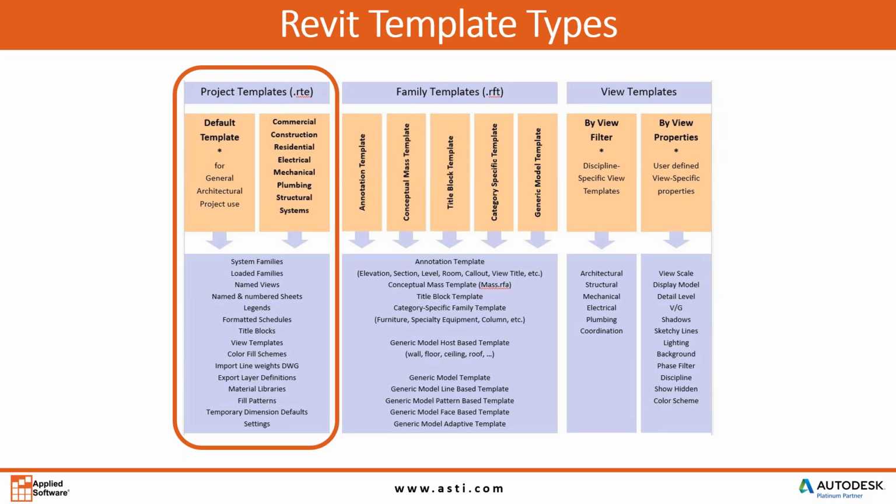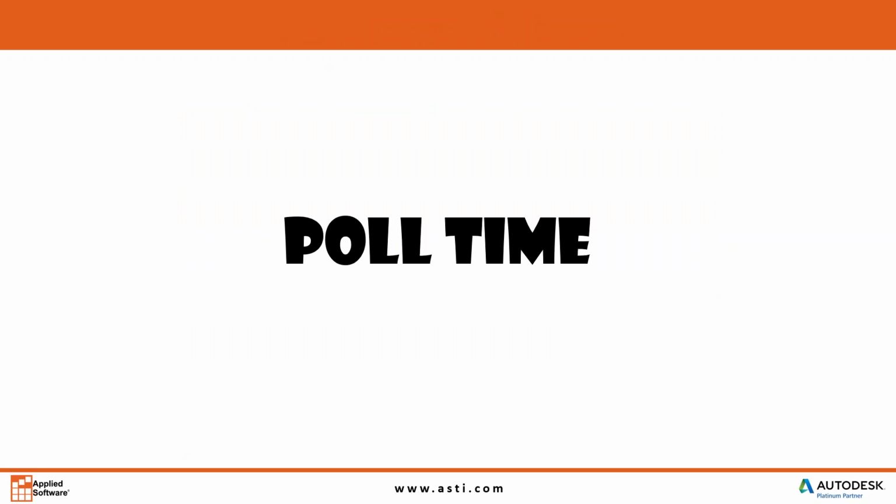Really, with templates and project templates in Revit, it's the number one rule. Coming from an AutoCAD-based workflow into Revit, with my very early experience, I didn't pay attention to the golden rule, starting with the proper template. And now, with all the training that goes around, that's really the number one rule in Revit. And we'll get into that and all the best practices throughout this session today.